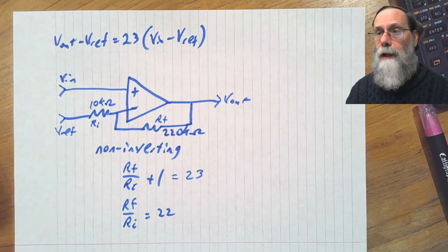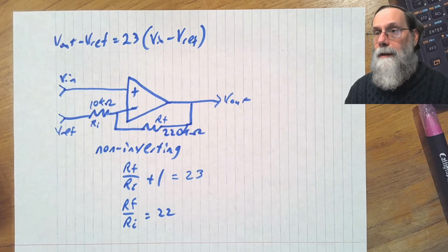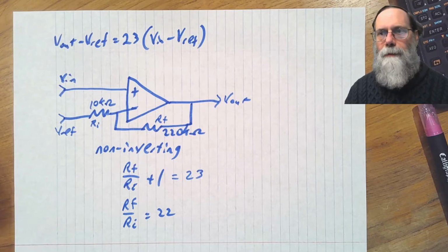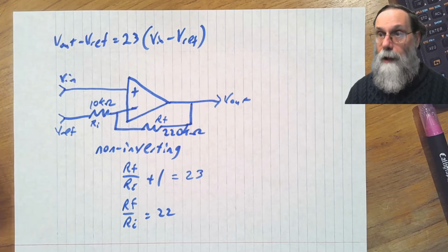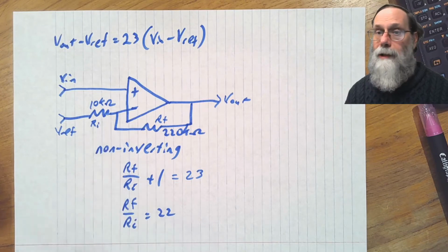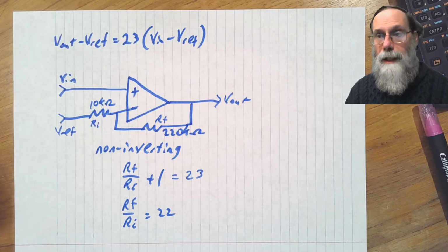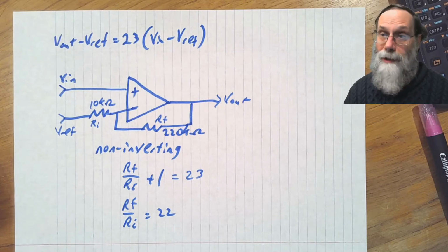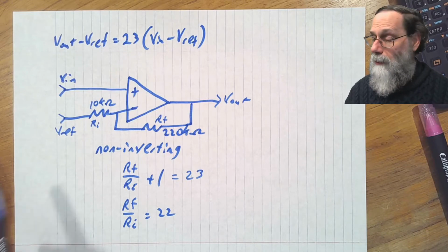We basically have only two things that are capable of providing current in our current repertoire of devices. There's a power supply and there's an amplifier. Power supplies are kind of expensive. We generally don't put in power supplies unless we need a lot of current. And generally for VREF, we're going to be hooking up to things like this where the current demands are going to be pretty modest, so we're not going to need a full power supply for it. Also, a clean power supply, one that doesn't have any fluctuation, is kind of expensive. So what we would like to do is take VREF from an amplifier.